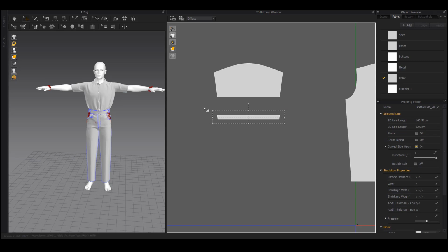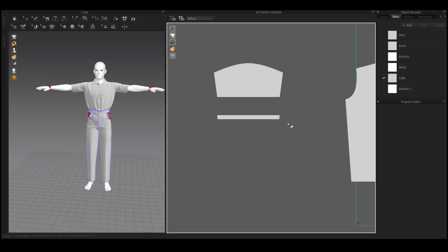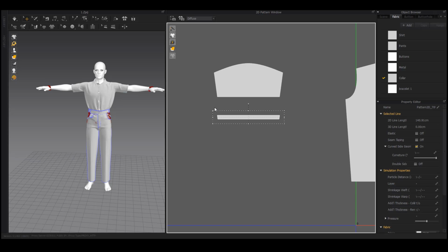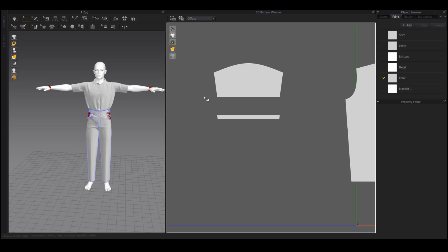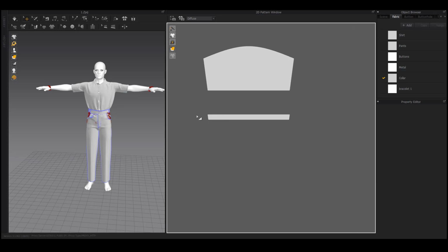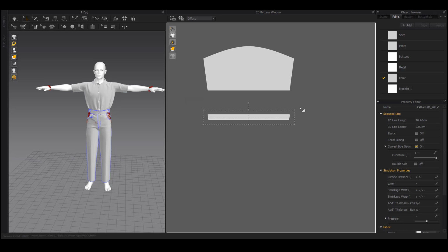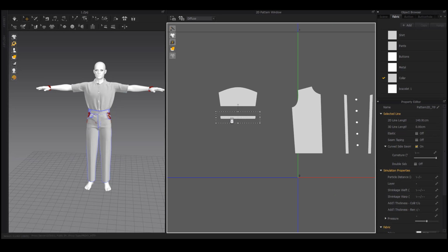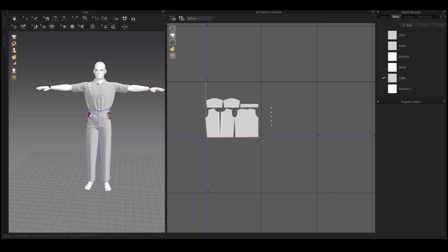If it is necessary to have several clusters of higher quality separately, we should increase the size of these clusters, and it is better to choose parts that do not need high quality and reduce the size of their clusters. There should be more space for the rest of the clusters. This method optimizes the system, and gives higher quality textures when making materials. When making UV, care must be taken that the clusters do not cross the UV boundary line, and that the clusters do not overlap. The next step is to prepare the model topology.